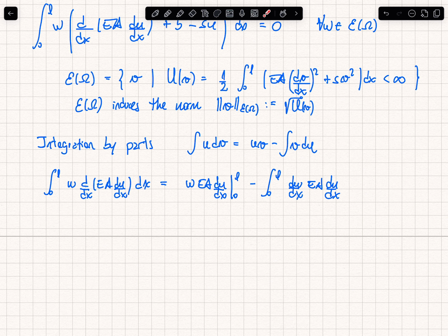And we looked at all of this in the nonlinear mechanics class, if you remember. So this term here, EA du/dx, is simply the axial force. And now I need to evaluate that at 0 and at L, right? So basically, by simply doing integration by parts and by balancing derivatives, because now I have a single derivative on the test function and a single derivative on my u function, those are balanced, and this has nice features.